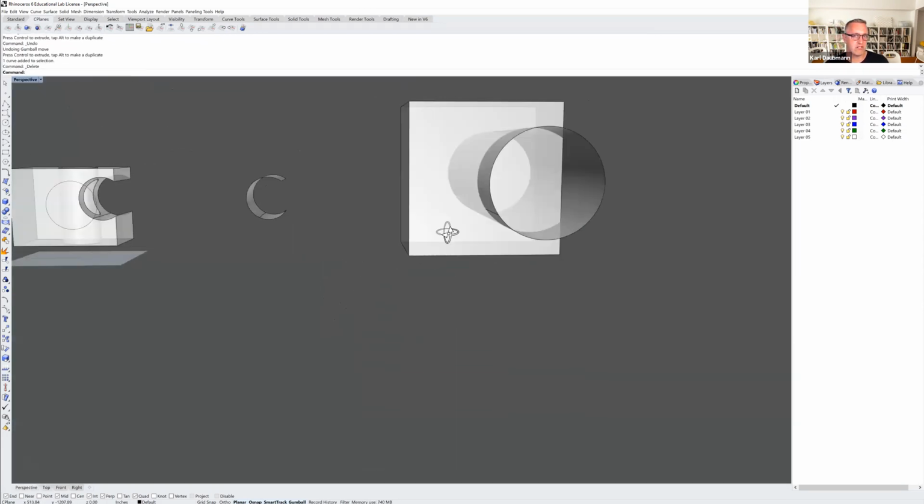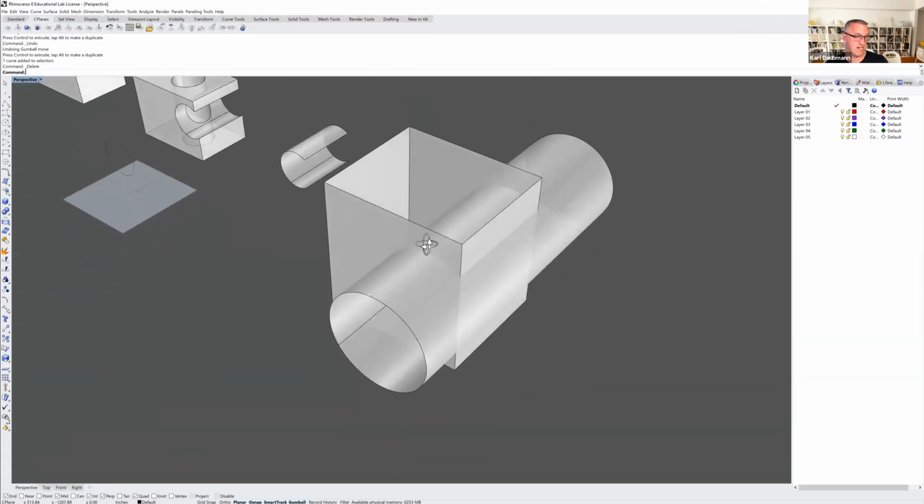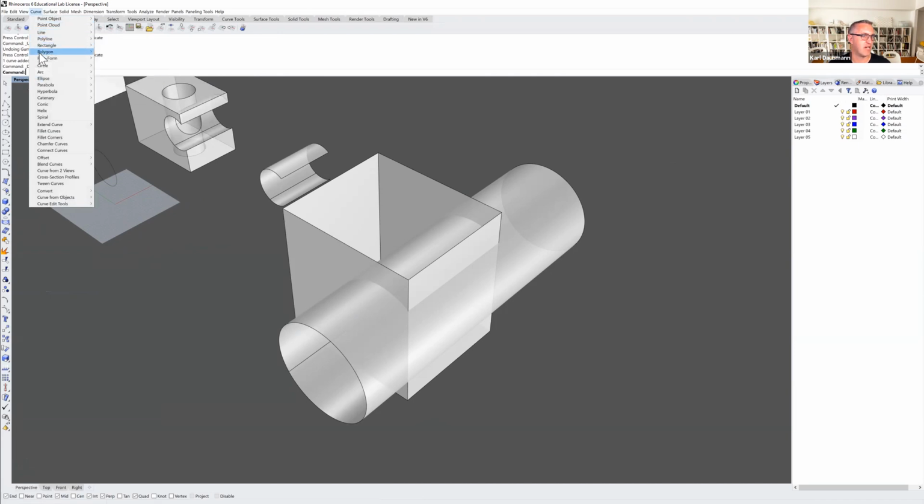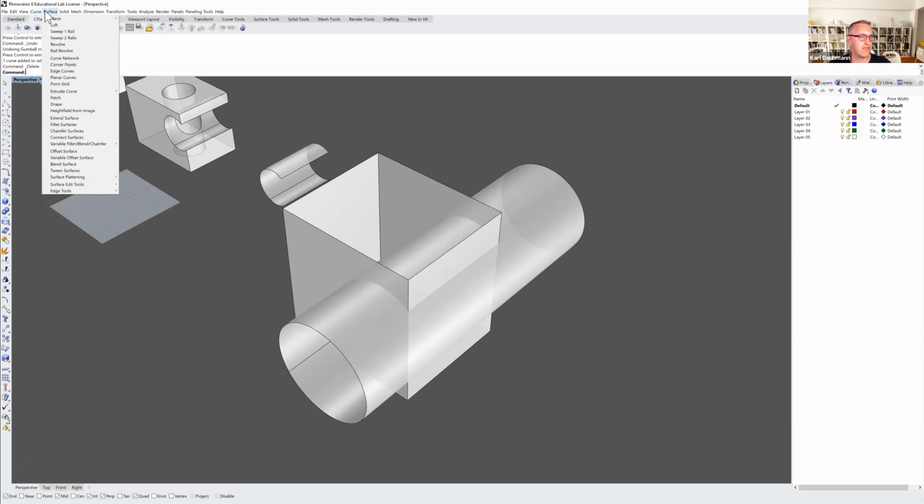We can do a couple of things here. Maybe we'll do one and then the other, right? What I'm getting you to start to understand is that we extruded one object, we drew something, we extruded that through it. We can get different types of geometry because Rhino is really good at moving between curves. And I say curve, but a curve can also be a line in Rhino speak. Line, polyline, rectangle, all of these are curves because they're just two-dimensional geometry, although I've also shown you that it can move into 3D, but curve, surface, and solid.